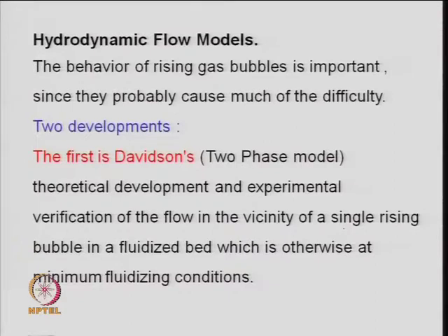So, this is the first one, which is known as a two phase model. There are generally two models which have been used, but this is the simplest one, a two phase model, where we are saying that there is a bubble phase and there is the emulsion phase. Emulsion phase means solid phase, and bubble phase means the gas bubble which has some solid surrounding it.